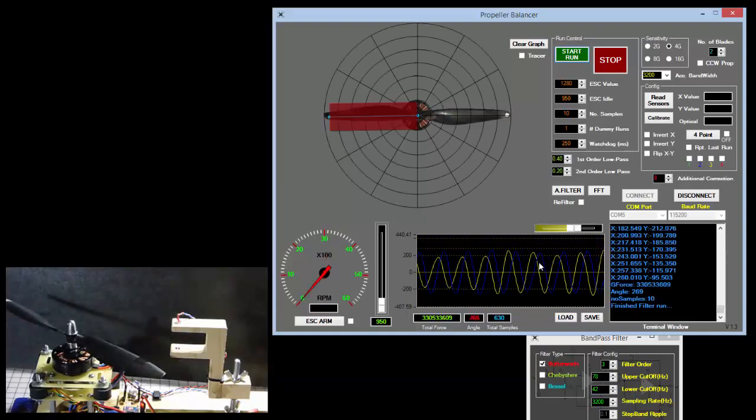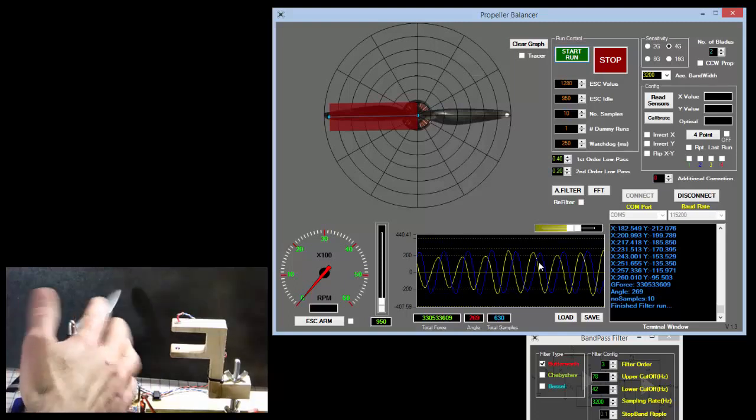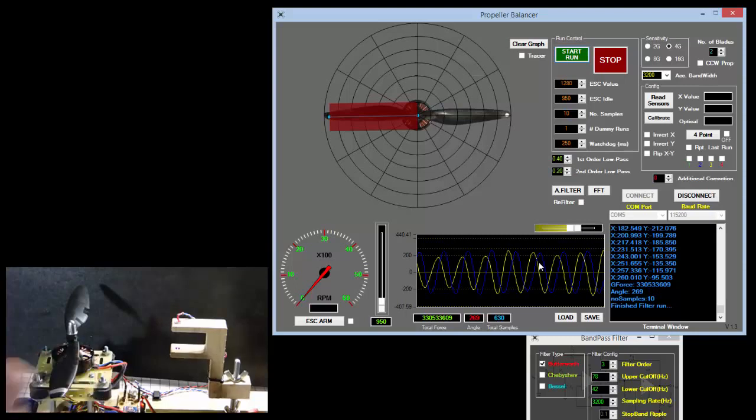Okay, look at that. It is absolutely razor sharp, spot on, accurate. By flipping the blade and with our filtering, it automatically pointed with extreme accuracy, within even 1 degree here at the 270 degree mark, which is exactly where we placed the tape. I'm just amazed, actually, by how much incorporating DSP filtering into the software has improved its accuracy.